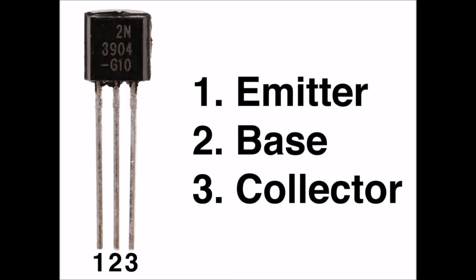Figure 22.4 portrays the situation as a graph. Once current starts to flow in the collector, increasing EB a tiny bit will cause the IC to go up a lot. However, if EB continues to rise, we'll eventually arrive at a voltage where the curve of IC versus EB levels off. Then we say that the transistor has reached a state of saturation. It's running wide open, conducting as much as it possibly can, given a fixed potential difference between the collector and the emitter.